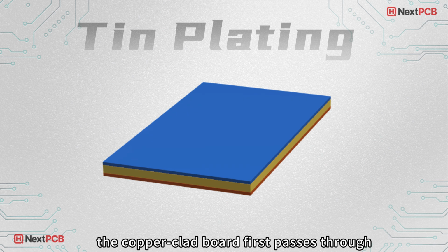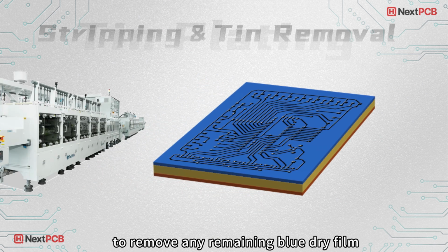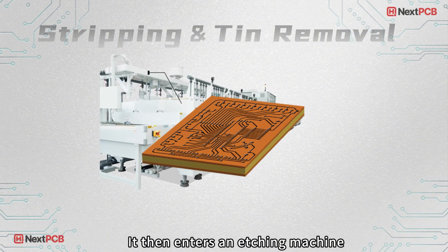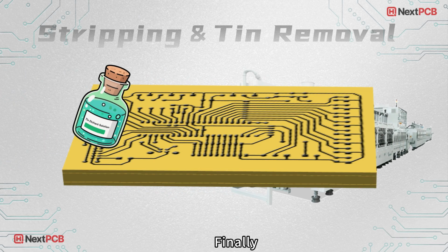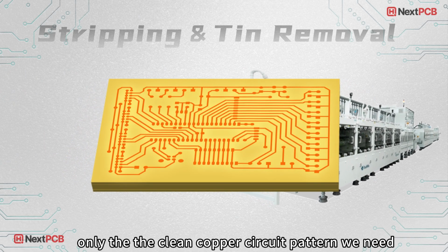After electroplating, the copper-clad board first passes through a stripping machine to remove any remaining blue dry film. It then enters an etching machine, which etches all copper not protected by tin. Finally, we strip away the tin coating, leaving behind only the clean copper circuit pattern we need.